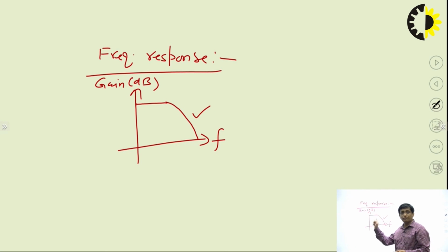But here at low frequency the gain is highest, the gain is not decreasing because we are not using any coupling capacitors. And this maximum gain that we have calculated is 107 dB. Although I have directly mentioned the value, you can calculate it just by calculating AV1, AV2, AV3 and multiplying them. You will get around 107 dB for a particular load resistance, right?